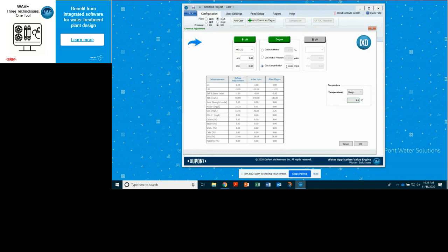And if we just go back to here, I can set this to a very low number. And I have so much acid in there, even though I take out all the CO2, I haven't budged the pH. So that's why on a demineralizer where you're working with a very acidic stream, this isn't really critical what value you put here. But if you're working with a working mixed bed where your starting pH is near neutral, it is very critical to not over degasify, because you'll specify something that's just not reasonable, not possible.